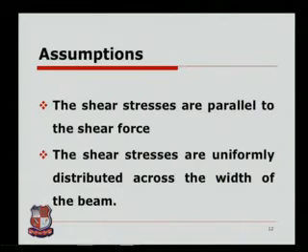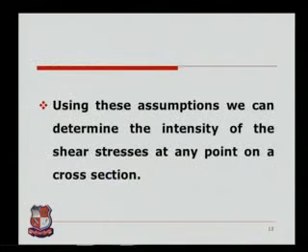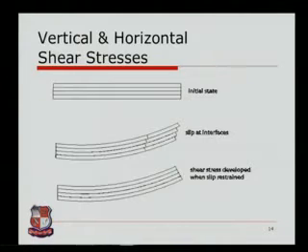Now to derive the shear stress formula we have to make certain assumptions. So shear stresses are parallel to the shear forces. Shear stresses are uniformly distributed across the width of the beam. Using these assumptions we can determine the intensity of the shear stress at any point on a cross section.